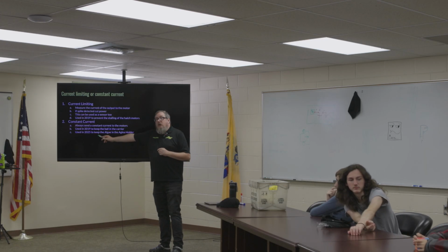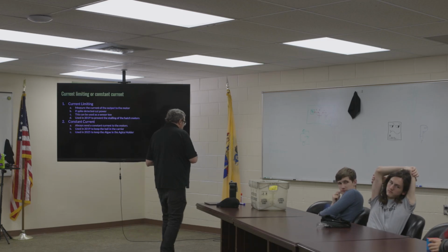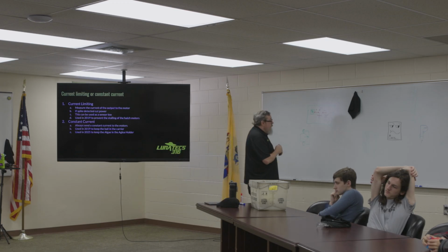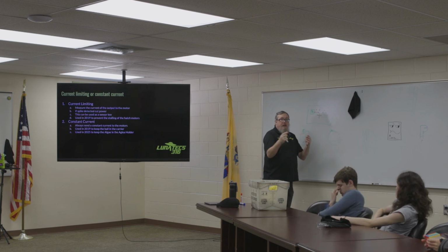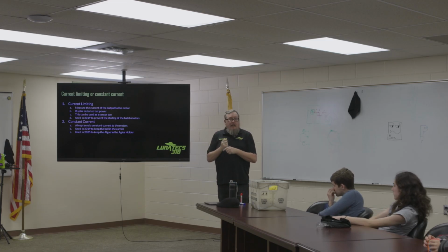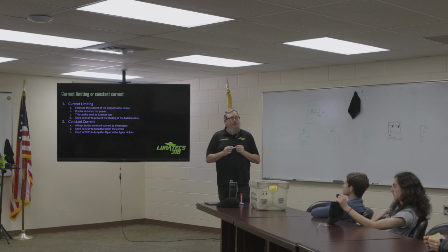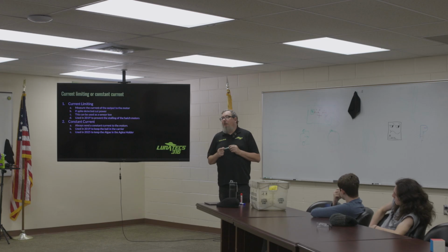Conversely, we can do a constant current. Why would we do a constant current? Anyone on this half of the room? Why would I want to constantly send power to a motor? So that it doesn't just drop it, it keeps it in and it's still gripping it, but it's not breaking loose. Exactly. So for example, this year with the algae intake, it would pull it in, and it would constantly give a little bit of power to the motor just to hold it in. And it would also make that horrible sound. Have you guys heard the motors do that high-pitched sound before? Maybe. That is the motors telling us you're doing something wrong, but we're not listening.